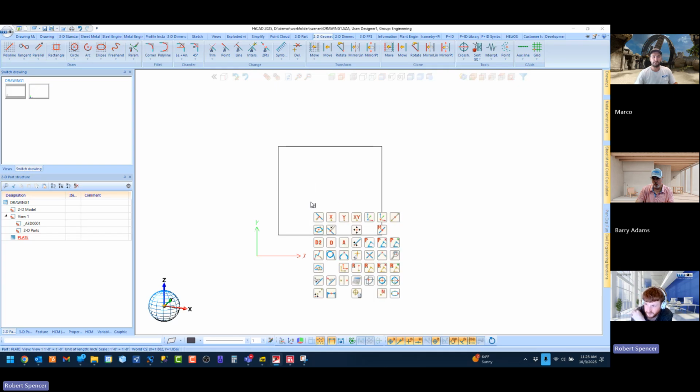If you hit enter on your keyboard, you will access a bunch of point options, is what we call these. And we'll slowly get to these one by one. Feel free to explore on your own. But two most commonly used ones are going to be either this from point, give a reference point, and we give it an X and Y offset from that, or a midpoint. If you want to calculate, for example, the middle of this, you could say from corner to corner, or midpoint here to midpoint at the bottom. But for this circle, we want to use this from point.